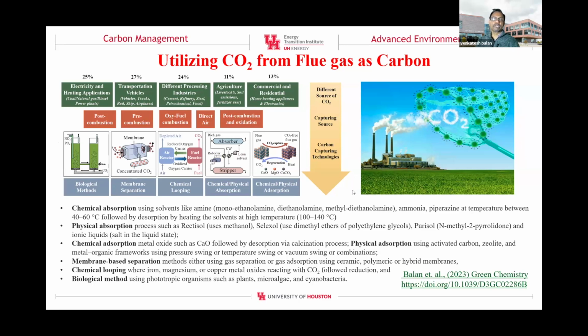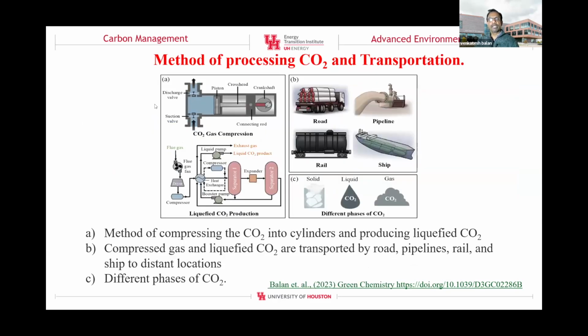So the overall goal is to capture the carbon dioxide and either store it under the ground or utilize it. I'm going to talk about how we can make money out of carbon dioxide rather than simply storing it in the ground. After we capture the carbon dioxide, it should be compressed. There's a cleaning process followed by compression, and carbon dioxide, as you know, can be in solid, liquid, or gaseous form.